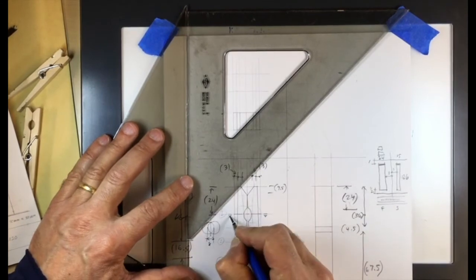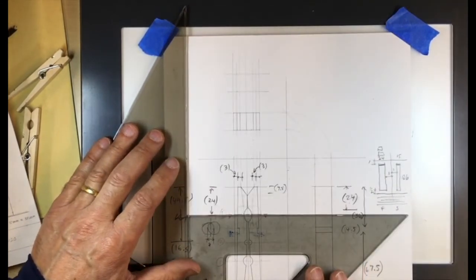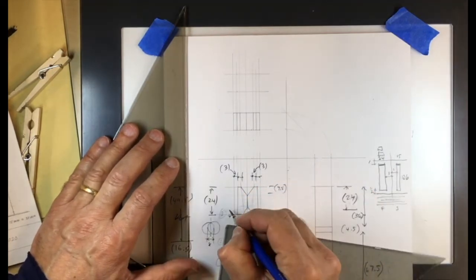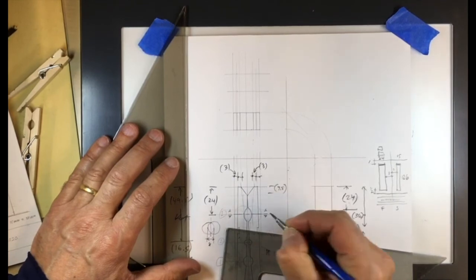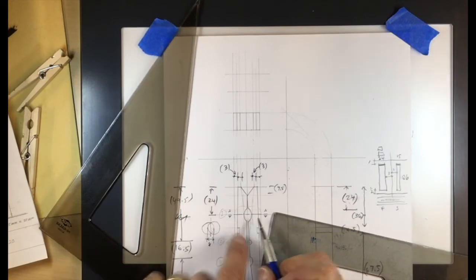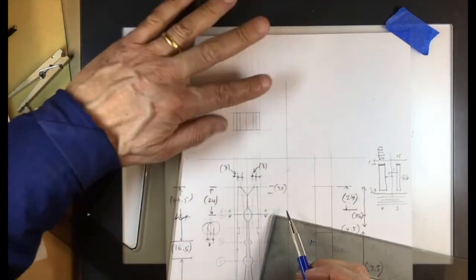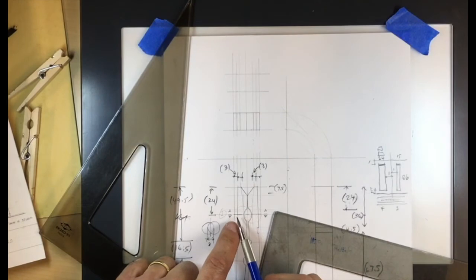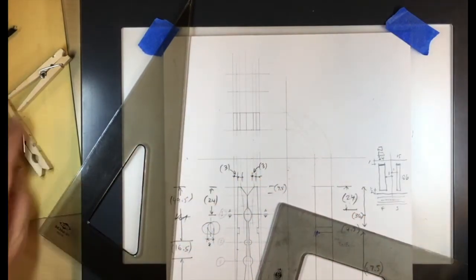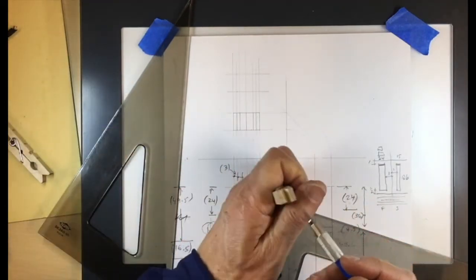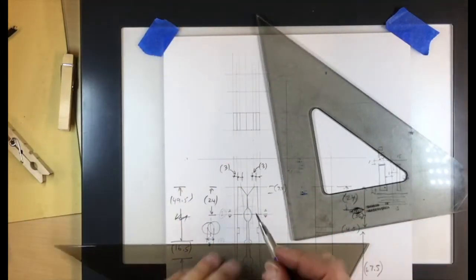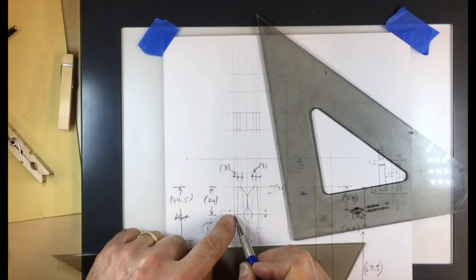And then I just put an A there and an A there because it's indicating what that line is. So what I need to do now, in order to draw the section properly, is project the points where that plane cuts. Basically, I need to project these new points, so wherever they are, I just pick them from here. And it's really just the corner, of course, because I can still see beyond it. And then the 4 spots where the circle part gets cut.